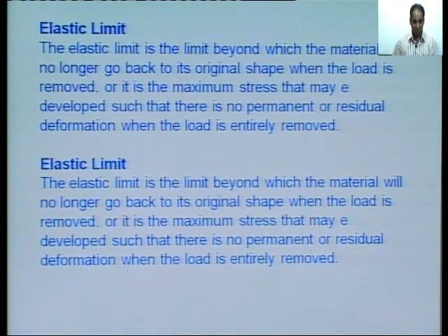And then from this curve I define the elastic limit. The elastic limit is the limit beyond which the material will no longer go back to the original shape when the load is removed, or it is the maximum stress that may be developed such that there is no permanent or residual deformation when the load is entirely removed. It means in this region, stress is directly proportional to strain. The curve is a straight line in this region.